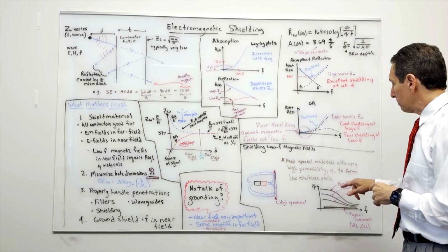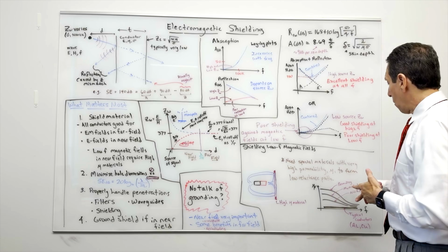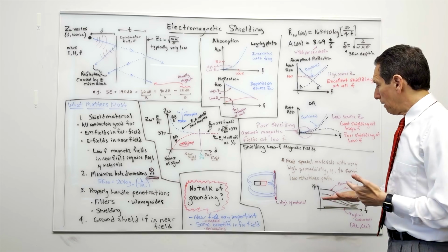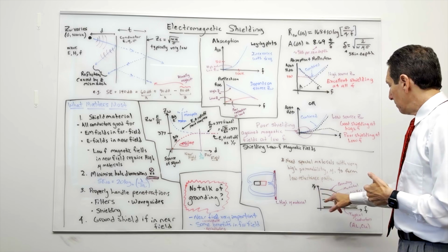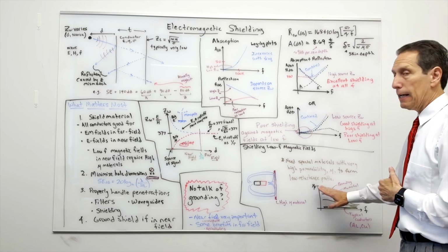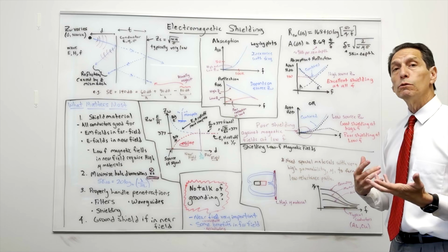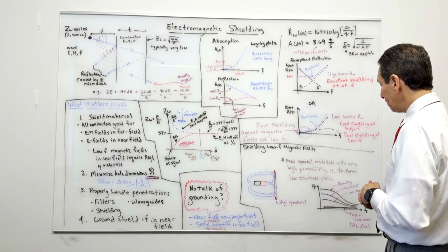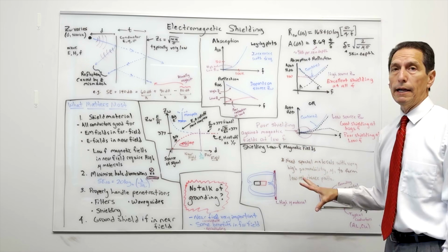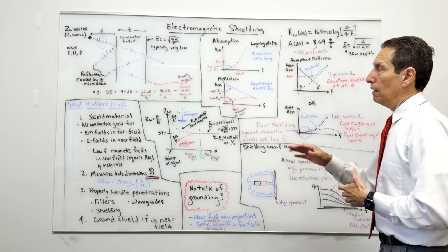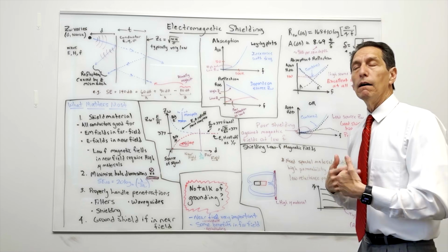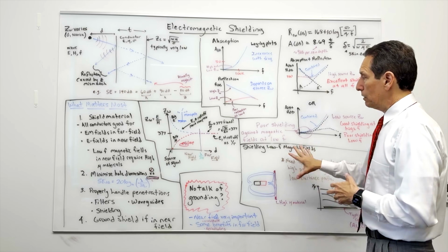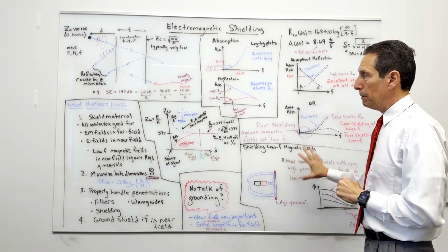So you'll see terms like permalloy, or mu metal, which people often talk about. But even nickel works pretty well. And so you get this relative permeability versus frequency, and they're very high at these low frequencies, and that's what you want, very high permeability for this to work for you, okay? So this is really the only way you shield against these magnetically dominated emissions, where you're in the near field of these loop antennas: using these high permeability materials.